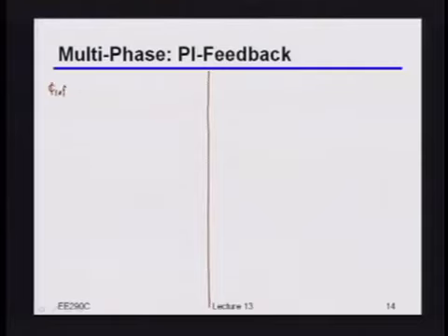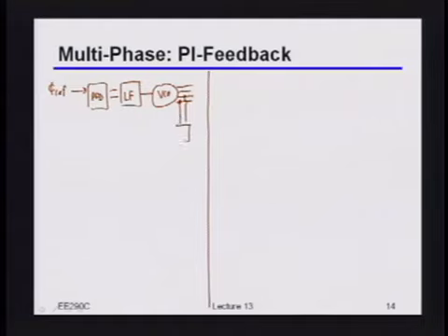So the first one is still a very similar idea. We're still going to be essentially hacking things in the PLL. But this time, instead of mucking around with the charge pump itself, what we're going to do is take those multiple phases from the VCO, and this time I'm actually just going to put a phase interpolator. Instead of using that to directly generate the output, I'm going to use it to provide the feedback for my PLL. Where now, again, this phase interpolator here is, of course, controlled by the CDR control bits. Okay?